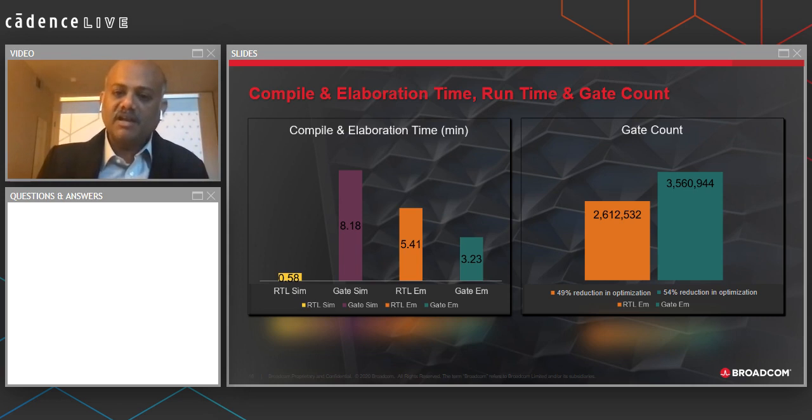So thereby it again optimizes. So these are the major areas wherein Palladium optimizes. So how it helps is when you have a larger design and a limited resource of the Palladium box, because we are trying to put the entire system here, not a single chip, right? It's multiple chips connected by SerDes chips. We are just trying to put the entire system into the emulator, right?